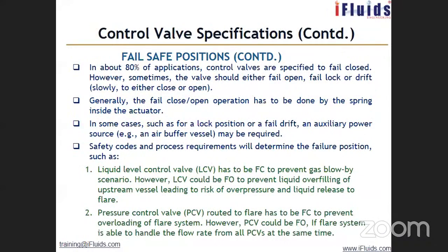So what are the conditions, fail-safe positions? In 80% of the applications, control valves are specified for fail closed. Close the control valve and don't allow the flow through the control valve. Sometimes the valve should either fail open, fail lock, or drift slowly to either close or open position.